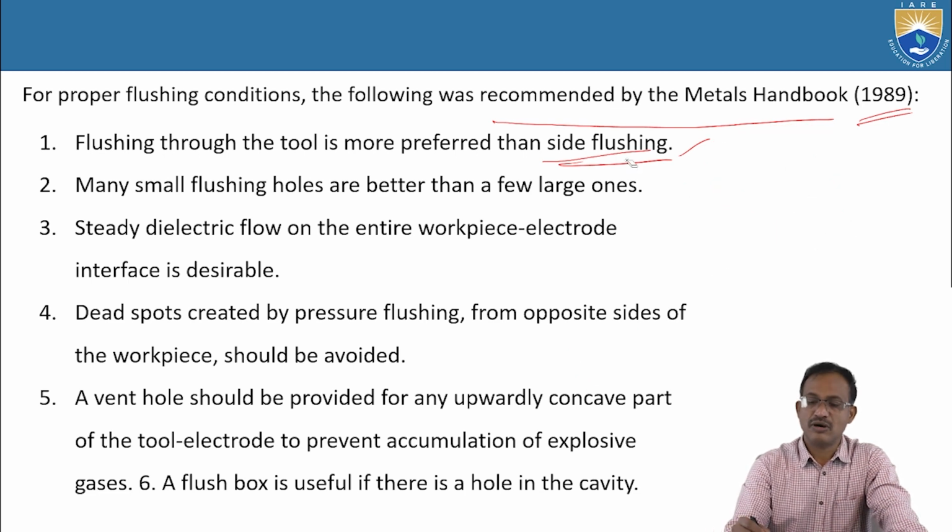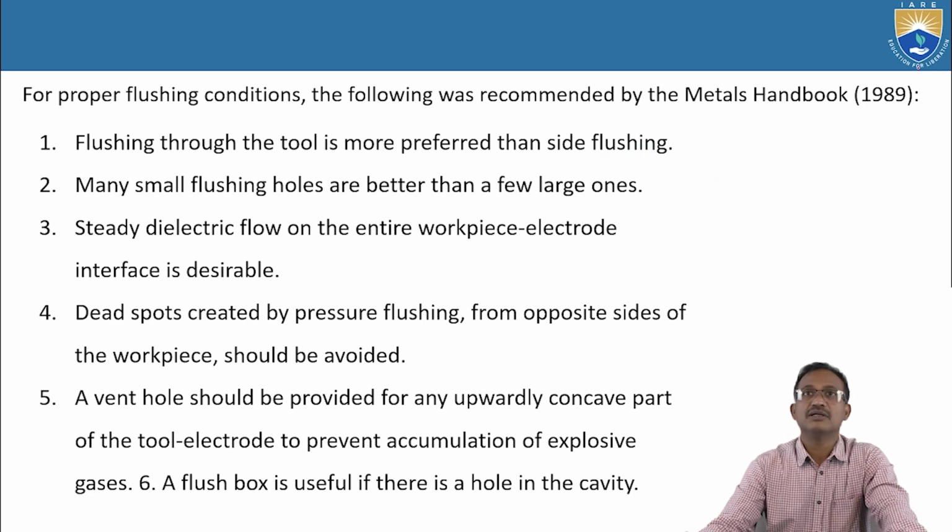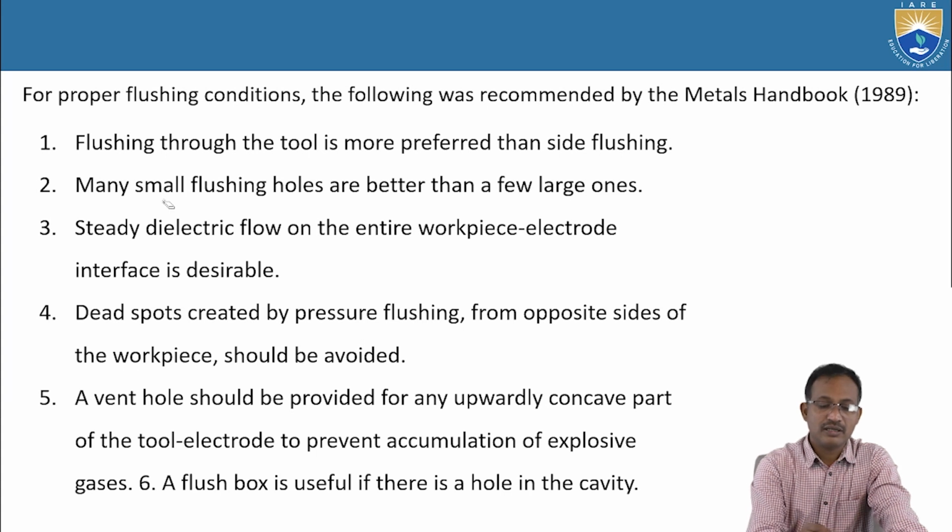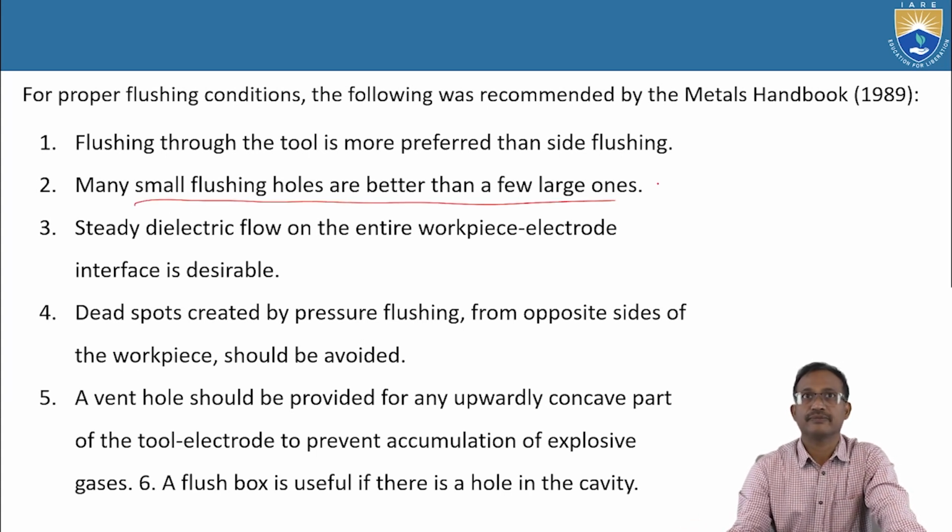Always small holes with large number will give better flushing. Many small holes are better than few large holes.